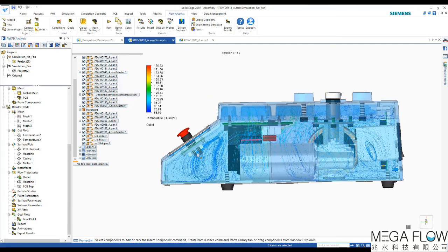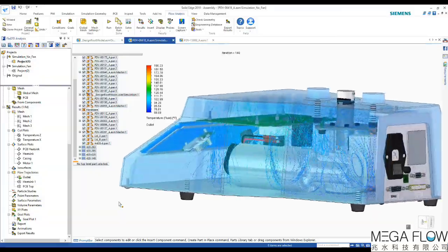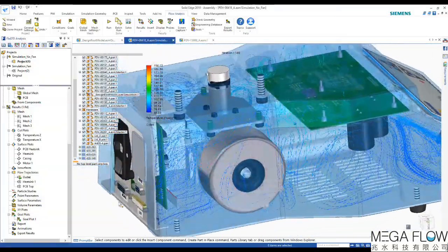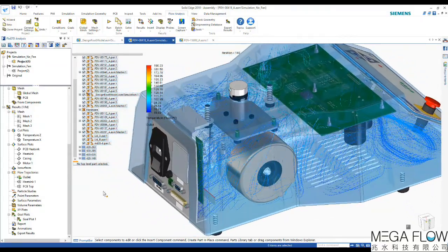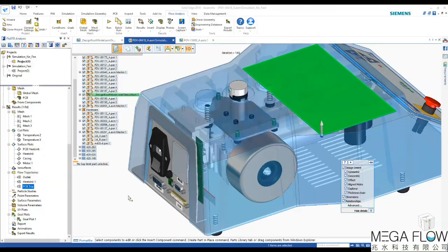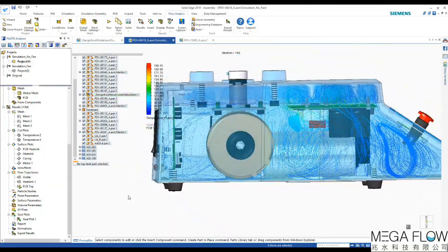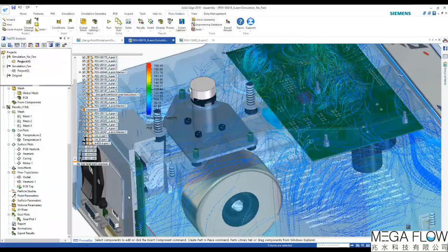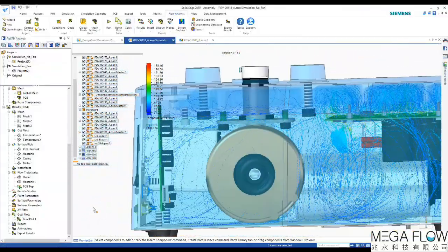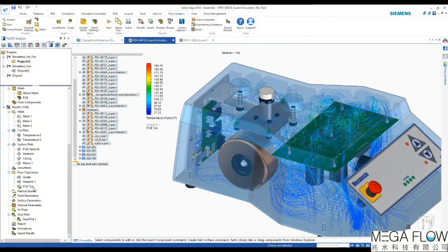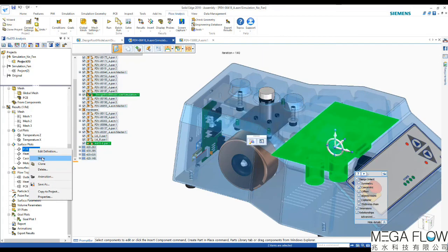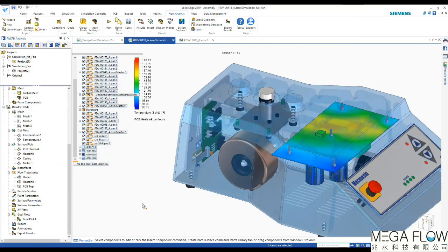Again, this model is pre-solved and we can look at the airflow in the enclosure. There is a lot of recirculation in the system and no real defined inlet to outlet flow. This is purely internal flow driven by buoyancy and temperature differences. If we show the flow coming from the top of the PCB, we can again see lots of internal recirculating flow, especially above the hot component. Some flow can be seen leaving the rear vent, as this is physically higher than the lower vent.